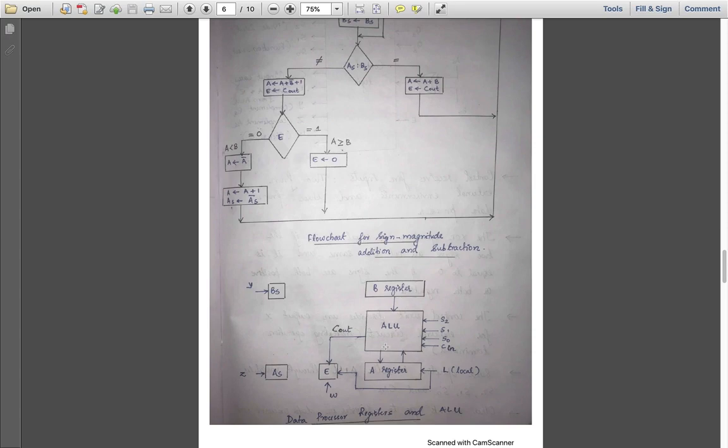Now whatever is being performed in the ALU, we have studied in the design of the ALU in the 5th module, that there are 4 control lines required to select the mode, select the operation, etc. So S2 is going to select the mode, whether it is an arithmetic operation or a logical operation. S1, S0 and CIN together will select the operation, whether it is an addition, subtraction, or a complement or transfer or whatever it is.